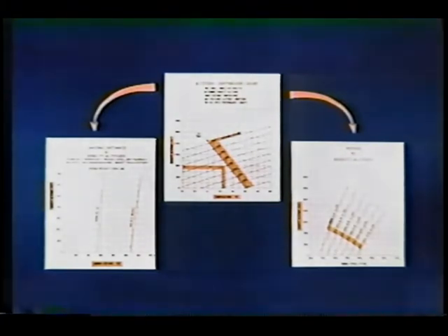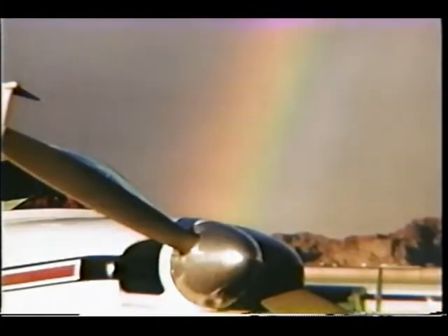Older aircraft publications use a two-step method that accomplishes the same thing. These publications provide a means of using pressure, altitude, and temperature to calculate density altitude first, and then to determine its effect on aircraft and engine performance. To be technically accurate, humidity is also a factor in density altitude, but since its effects are minimal for landings, it is not normally considered.